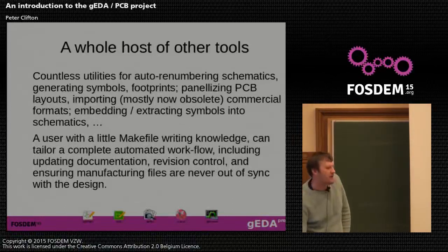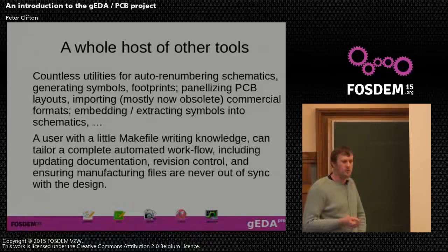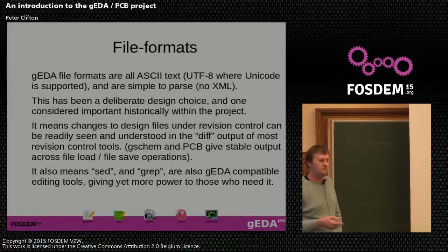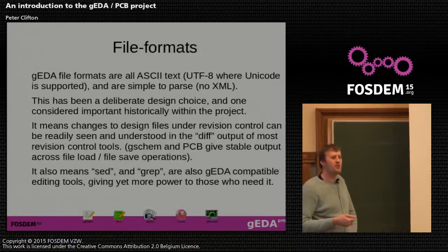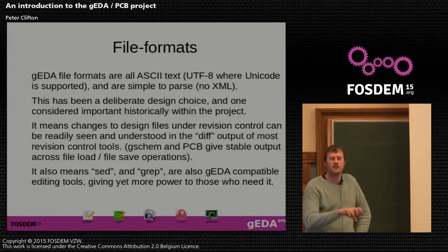File formats, again, another fairly core feature that people regard in the gEDA project as a design feature was that our file formats are ASCII-based. UTF-8, mainly, because I can say that, probably weren't UTF-8 when they were intended. But it allows people to then adopt things like sed and grep as part of their tool chain. Perhaps in some respects it weakens the position we have in terms of representing embedded graphics. We tend to base64 encode any embedded graphics we put in the files, but it does give us some flexibility when people actually go into the schematics and say, well, I want to put that via or the track at some exact location.